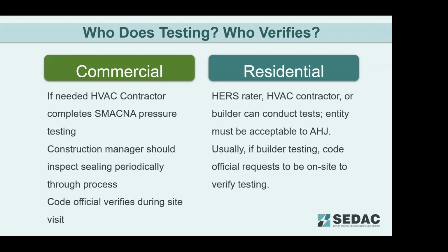So whenever possible, get that test done at rough-in. I've done a number of tests before we even had electrical installed, where I had to bring my own power to power the fan. But by far, that's a better scenario to test in. So if there's any issues, you can fix them.